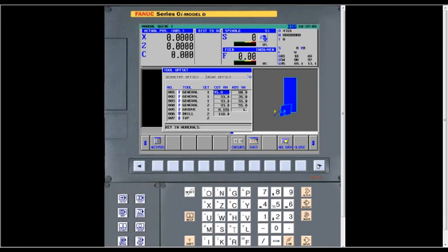All right. Now the next one, cut angle and nose angle. These are very critical, because if we put the wrong information here, you get all kinds of bad information when you actually make the program. As I said, the tool that I have in my machine, it's an 80-degree diamond tool. And with that type of tool, it always has 5 degrees of clearance on the front side.